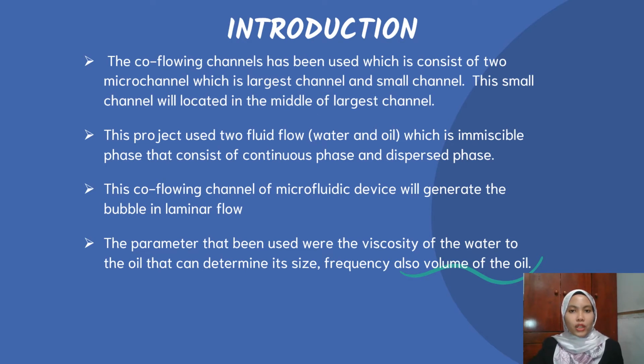This co-flowing channel will generate the bubble in laminar flow because it is easy to control. The laminar flow is formed because of the low Reynolds number. The low Reynolds number comes from the bubble forming at a small length scale, which is in micron size.